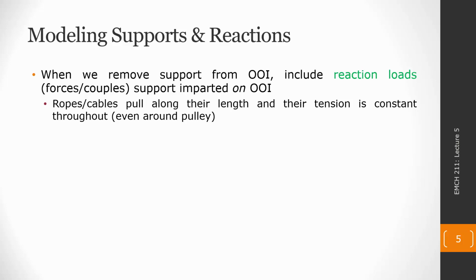But here we're using the load a little bit more generally. A reaction load or a reaction can be a force and or a couple that the support put upon the object that we still have. Now, we'll still have some things that remain the same like we saw with a particle. Ropes can only pull, cables can only pull, and they can only pull along their length, but we're also going to get more exotic types of supports as well.